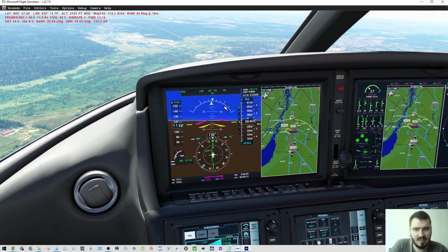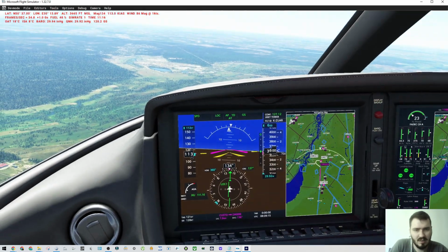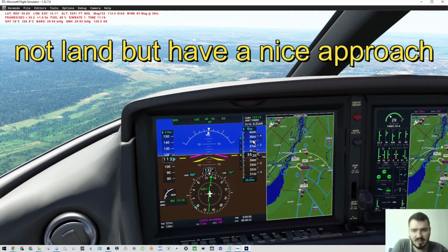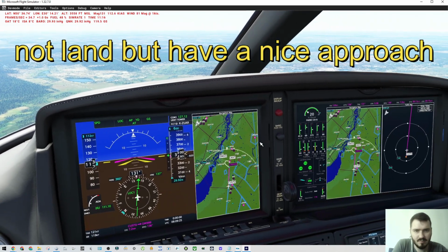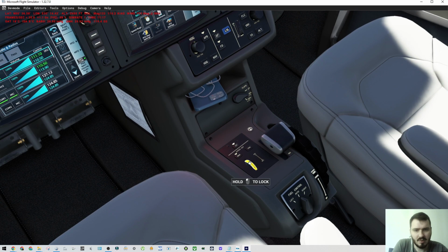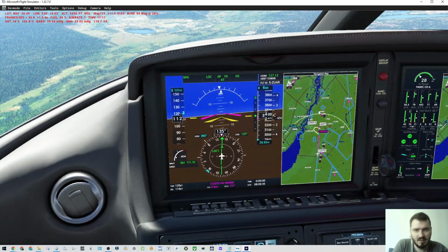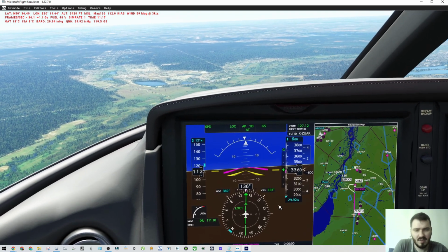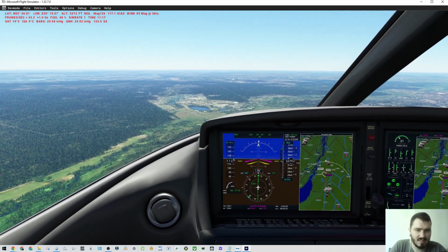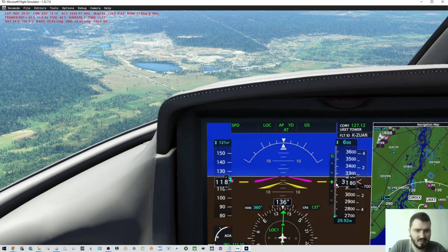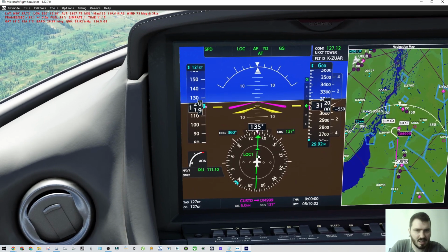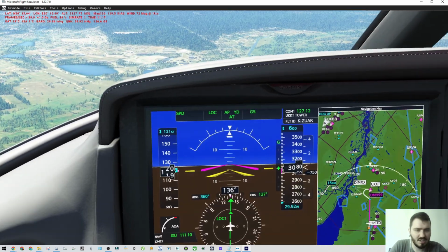Okay, the aircraft starts to descend now. Reduce power. And I expect that we will automatically land on this runway. Maybe we can set a higher speed because it's just for our experiment, just to be faster. Okay, and I will expedite this video in order for it to be faster. And also you can see that the green ramp actually appears here, so we are on glide slope, and here you can see that we are on localizer, and the landing course is established.